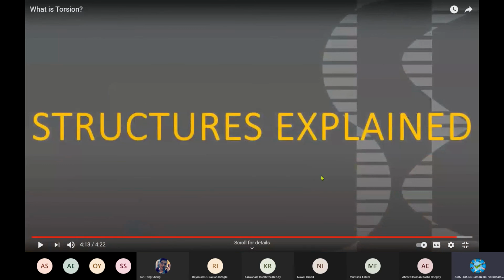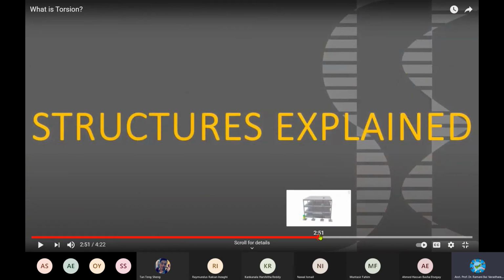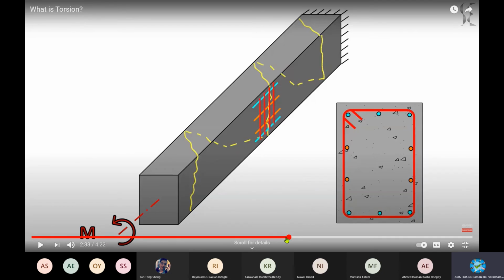Okay, can you answer my question? In reinforced concrete, I don't know whether you studied last time or not. Which portion is taking the torsion load? This is important when you go for RCC design also, the same thing you will do. You have to know which is taking which type of force, which is taking tension, which is taking compression, which is taking shear or otherwise rotational moment.